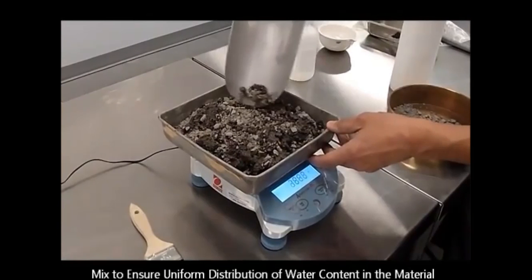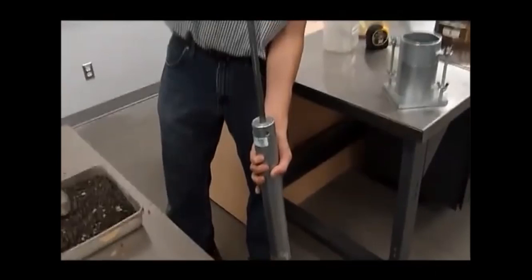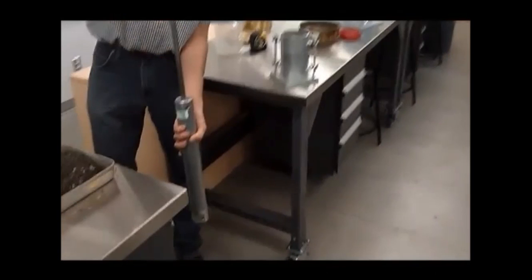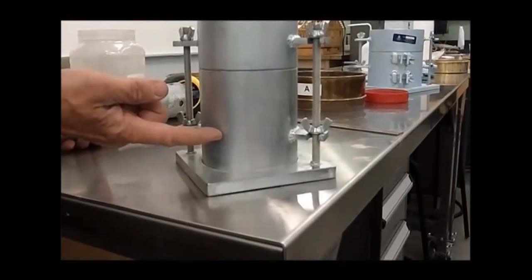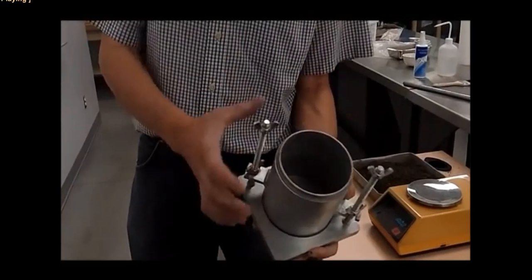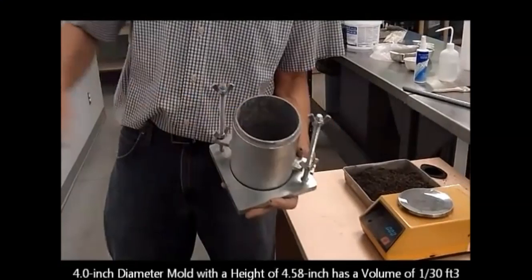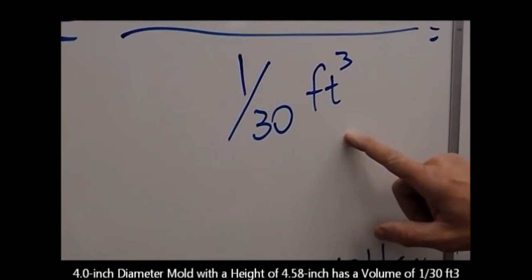After mixing the soil, I'll take some soil in the mold. So this is my rammer. Its weight is 25 Newton or 2.6 kg. So I'll first put the soil in the mold such that after compacting the soil, it will fill 1/3 of the mold.